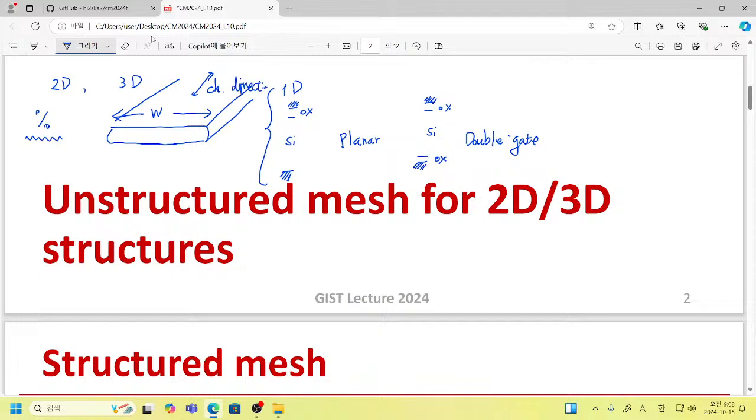When we consider the thickness T of our nanosheet, usually this value is around 5 nanometers or sometimes 4 nanometers. And how large is the width? It is on the order of several tens of nanometers. So the aspect ratio is quite high in this horizontal sense.